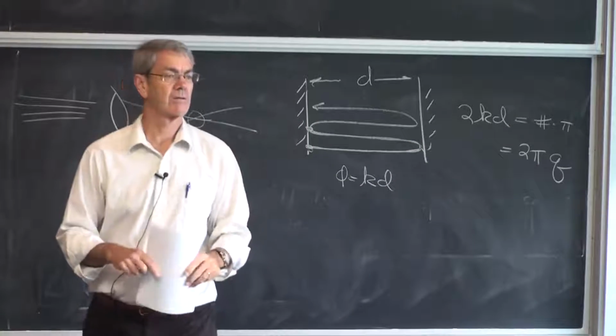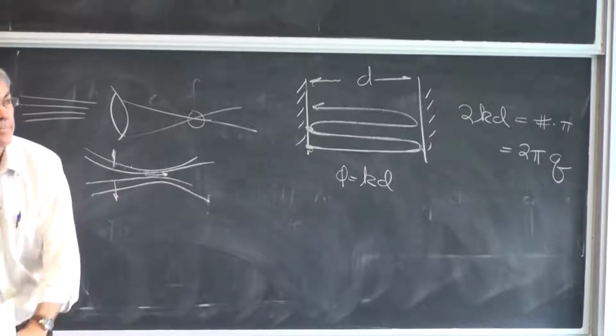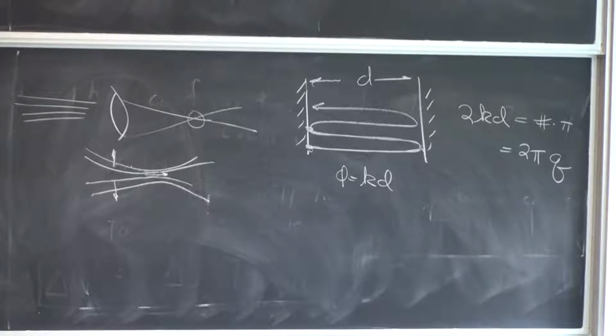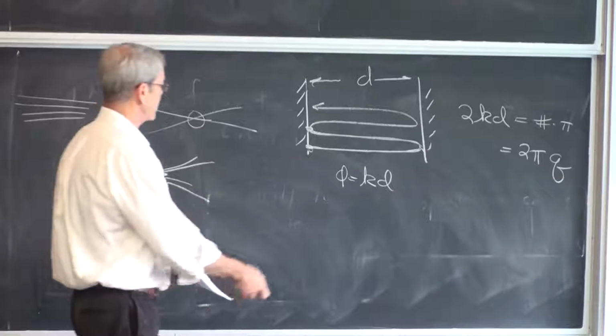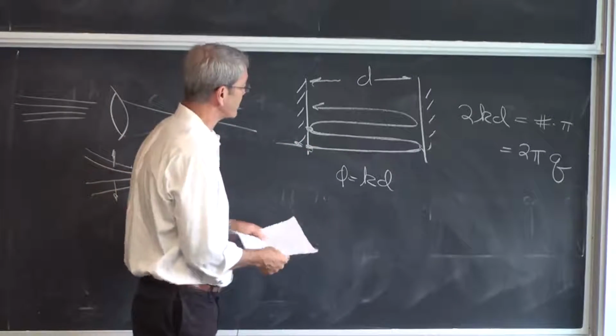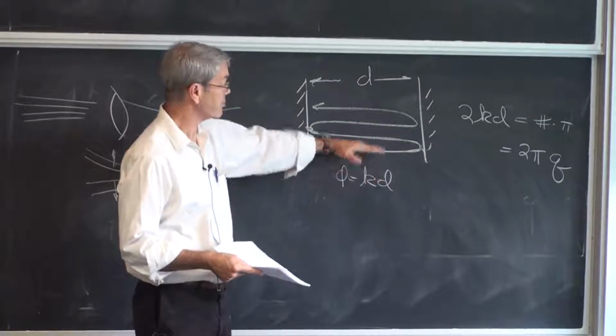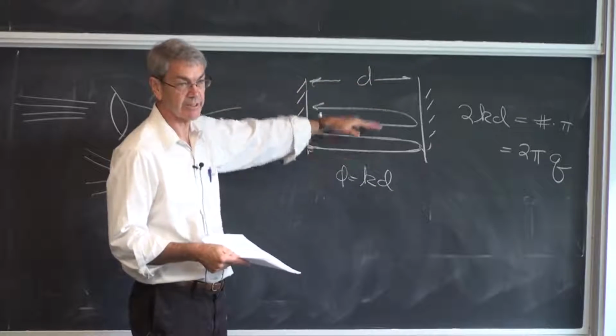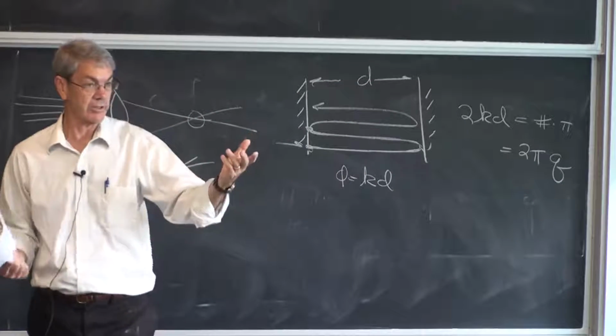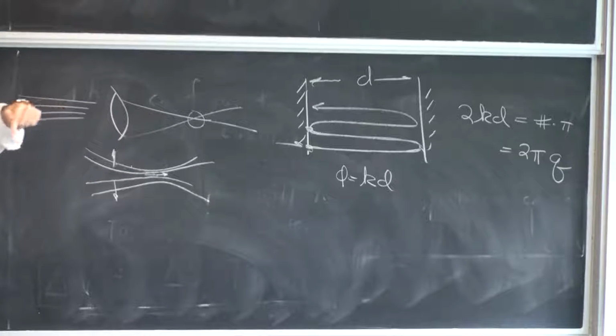But if it is in phase, you say it accumulates, so does it increase in energy? Yes, it will. If we keep feeding it, we'll get to that. If I keep putting energy in and it keeps running back in phase, the energy builds up dramatically in here. You see this in an RLC circuit. You take a very weak signal off an antenna, feed it into an RLC circuit, you build up a big voltage, you store energy in that. So it's the same idea. This resonance is a very common phenomenon.